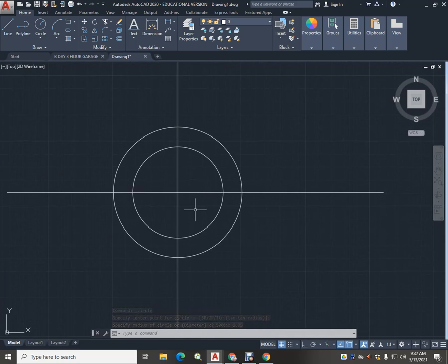Now we have slots that we want tabs to stick out on the end so that it matches the nozzle as we undo our gas cap, and then we want to be able to turn it 45 degrees to lock it down.